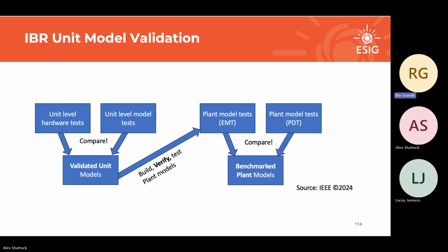So that's a perfectly fine control hardware in the loop thing. And that was actually a very contentious piece in the IEEE process: do you actually validate and type test a plant controller? The answer was, that sounds like a good idea, but no one wants to write it. So I wrote that section because I thought it was important, because it's half or more of the plant's operation. You're much more often operating in an operating point with the plant controllers in full control than you are in any fault ride-through mode, just over the lifetime of the facility. So it's very important for the plant controller to be validated as well.